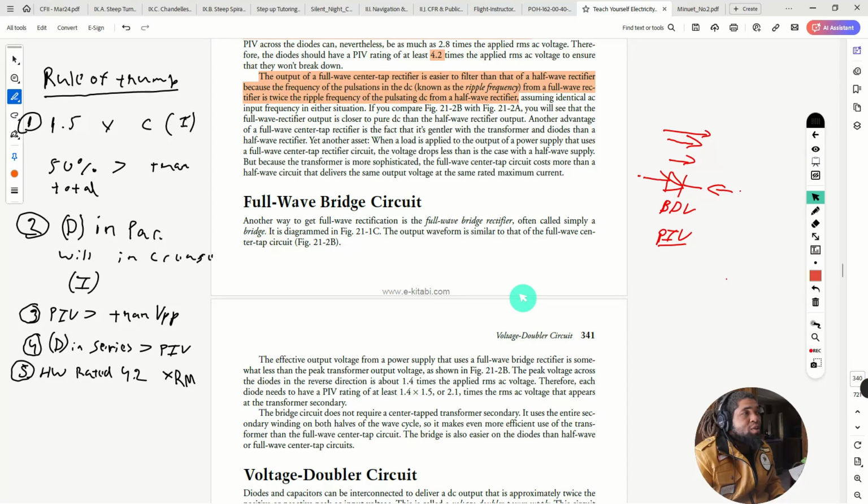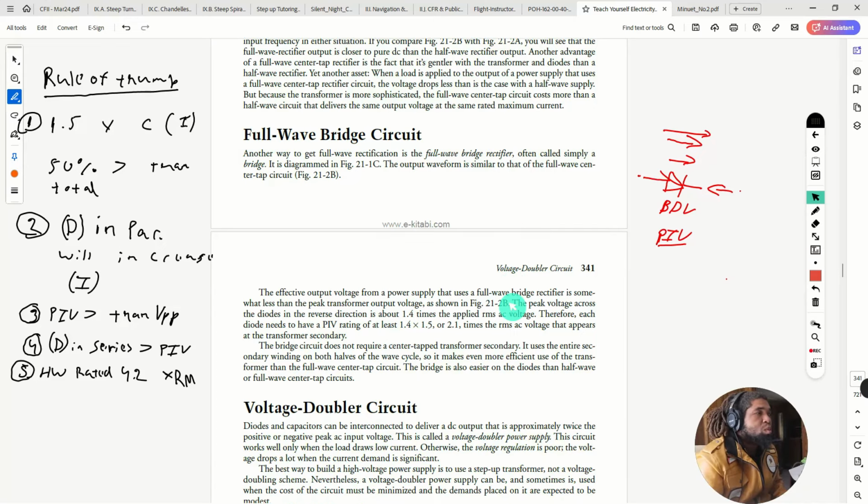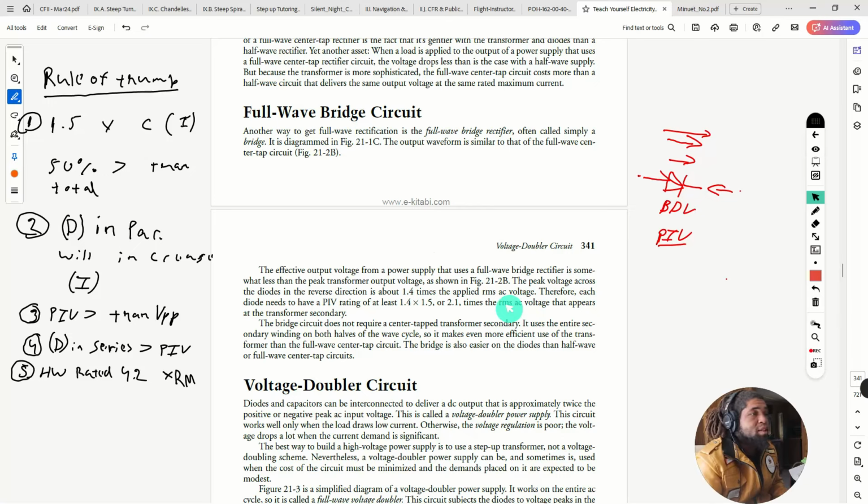And he's saying that, hey, if you have a situation in which you can get the kind of current you need from a half wave rectifier, you might as well just do it with a half wave rectifier, because it's going to cost you less for a transformer. Just as in the case of when I was talking about guitar amplifiers that use fixed bias and need a tap for negative voltage, usually they're tapping that on the transformer that's already existing. They're not putting in another transformer, to save money, essentially.